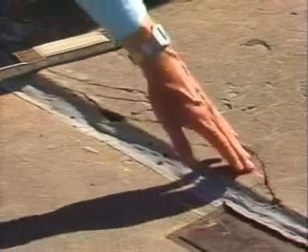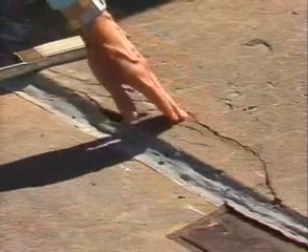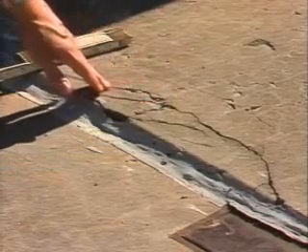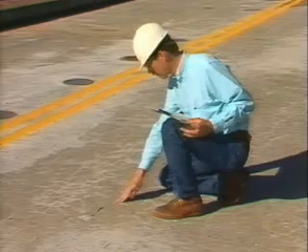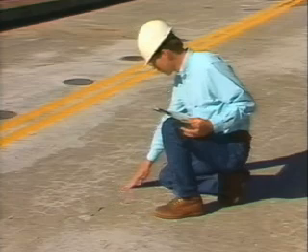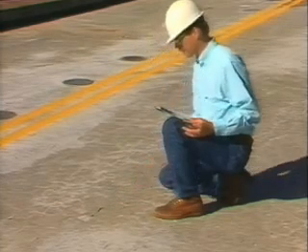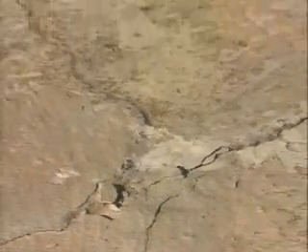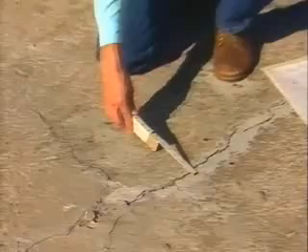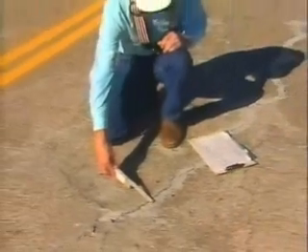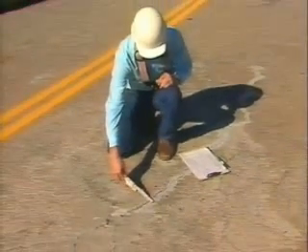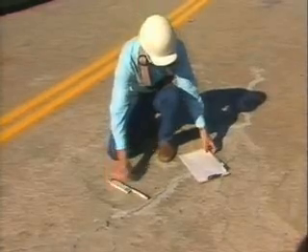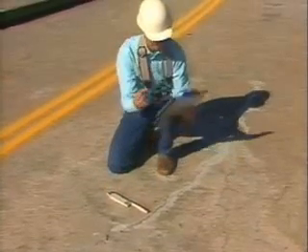Some of the cracks encountered when inspecting a dam are serious. Others are not. Be especially concerned if a crack has appeared since the previous inspection, if a crack has enlarged, or if there is displacement along the crack. Measure the length, width, and any displacement along the crack. Photograph it and record its location in your notes.